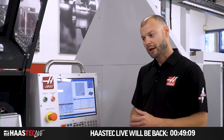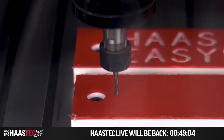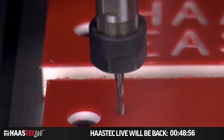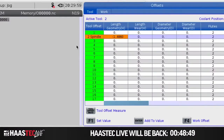But before I do that, I'm going to move my machine away from the stock a little bit, in case I entered any bad numbers. I want some time to push stop. So let's do that. First thing I'm going to do is move Z away from the table a little bit, just in case I got anything wrong. This will give me some time to realize that and stop it before I crash anything.